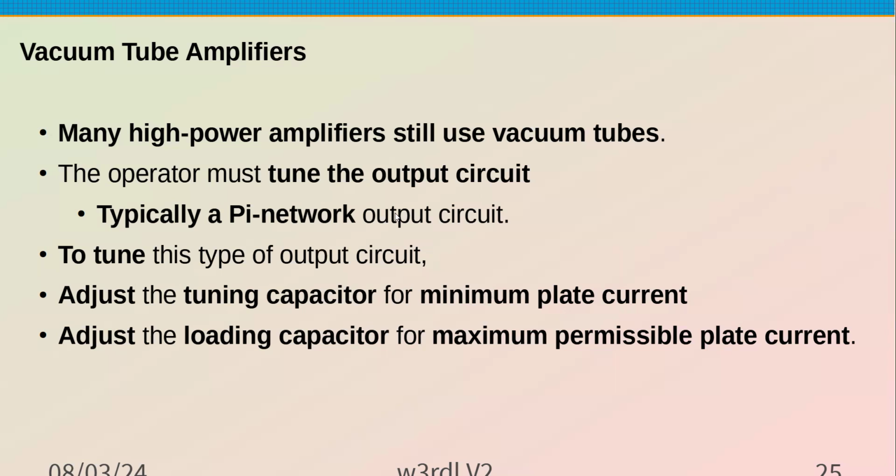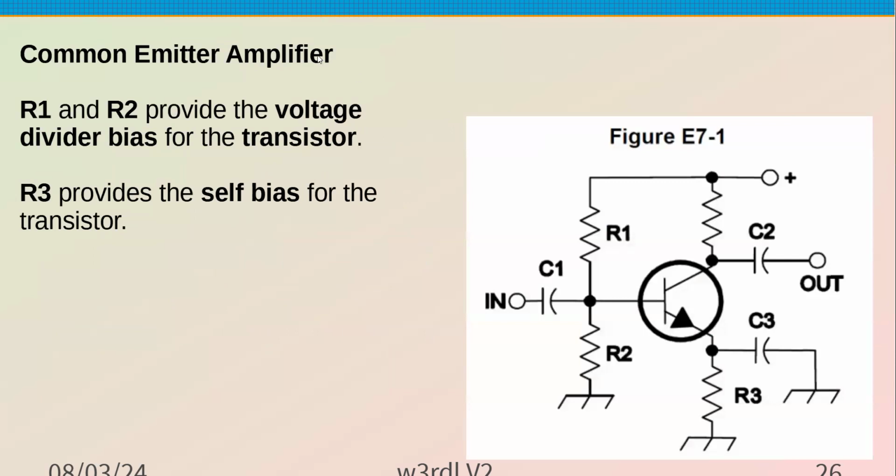And you wind up twiddling two knobs to adjust the grid current and the plate current, and dip them and all that good stuff to get the maximum power out without exceeding the plate current, or the tube starts to turn cherry red. They don't like to do that for very long. You don't have to do all that stuff with a solid state. In fact, a lot of the higher end ones, it's totally automatic. You just turn it on, it adjusts everything, and away you go.